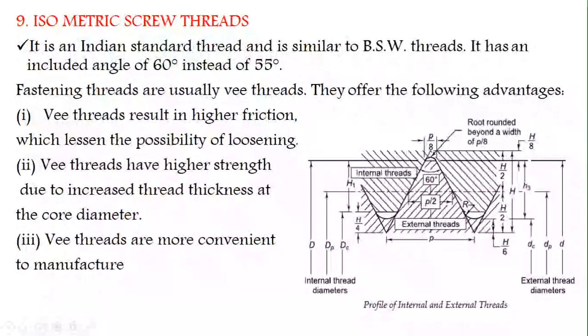Therefore, threads with fine pitch are more dependable than threads with a coarse pitch in respect to self unscrewing. Coarse threads are recommended for general industrial applications which are free from vibration.